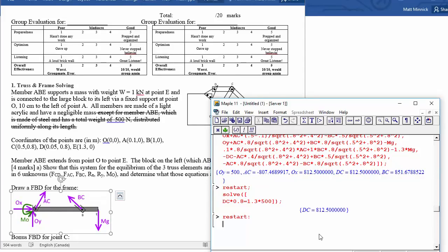And now what we're going to be doing is starting by typing in the position vectors for all of the different points. So RO is, let's check out this new package. This is beyond the Maple that we had before. With linear algebra. This is including a package in Maple, so adding in the linear algebra package, RO is going to be the vector object of 0, 0, like that.